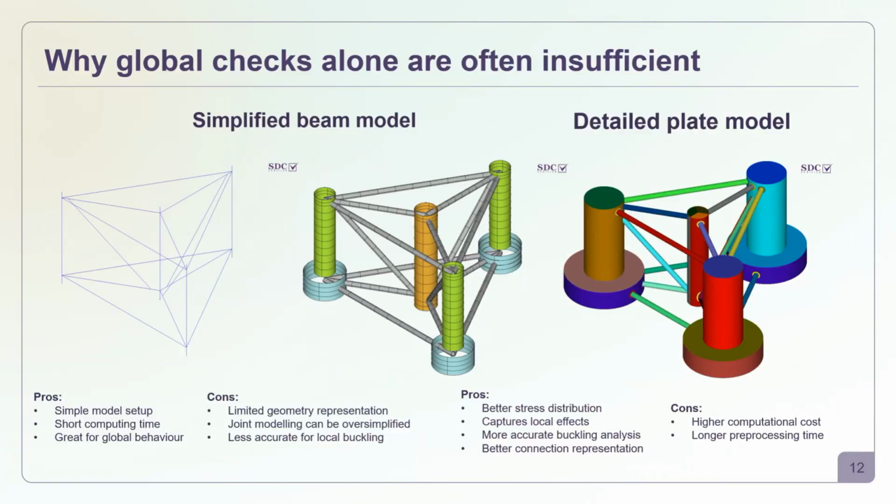However, as you can again imagine, there are some cons. It is very time consuming to pre-process the model, meaning to prepare the geometry, mesh the model with great quality, and so on. And it is also high in computational cost. It will simply calculate way longer than the beam element model due to the elements that are used. So yeah, it is important to decide with which one you want to start.